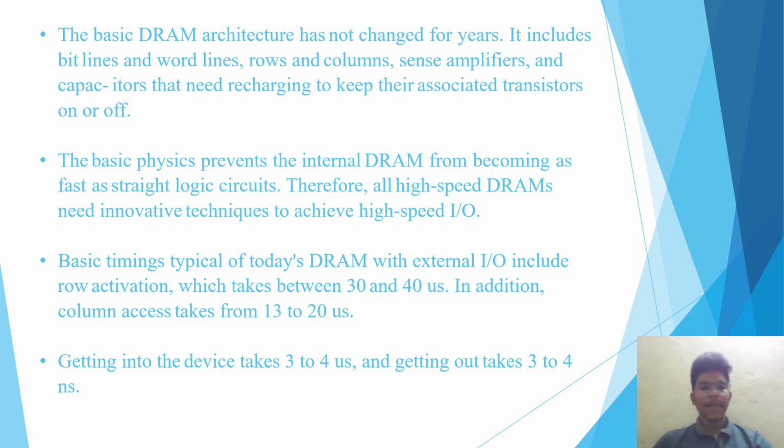The basic DRAM architecture has not changed for years. It includes the bit lines and the word lines, rows and columns, sense amplifiers, and the capacitors that need recharging to keep the associated transistors on or off. The basic physics prevents the internal DRAM from operating as fast as straight logic circuits. Therefore, all high-speed DRAMs need innovative techniques to achieve high-speed input-output.